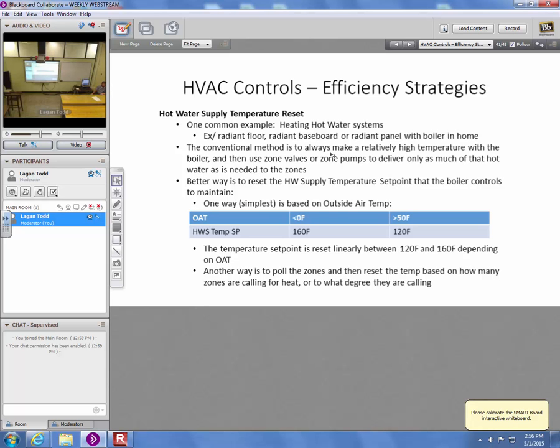Or an elevator is another one, constant head. It takes the same amount of energy to pull that elevator up from the basement to the top floor, regardless of how fast you do it. Power changes, but you're not going to get any energy saving. But for things where you have valves or dampers on fans, generally speaking, there's savings. In some cases, you have a better case than others to put variable speed on, but it will always save energy. It's just a question of will it save enough energy to pay for the retrofit.